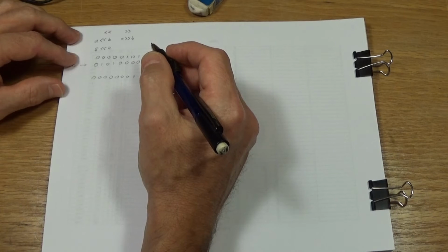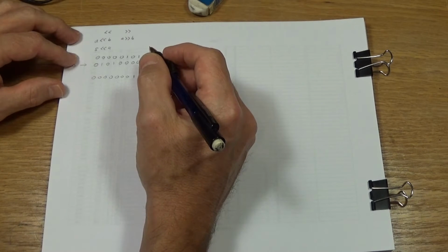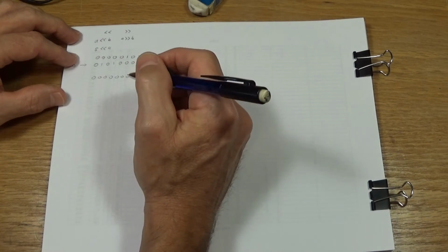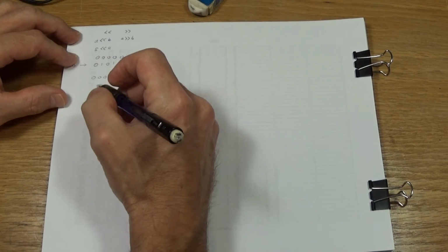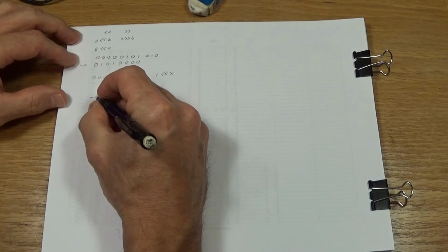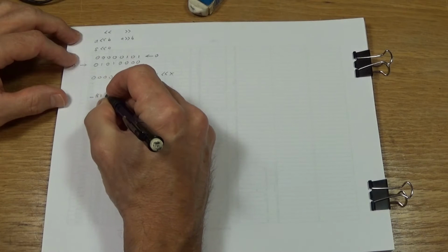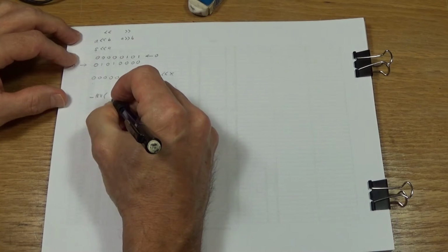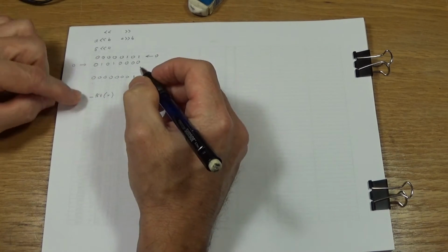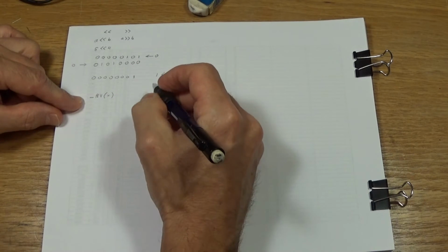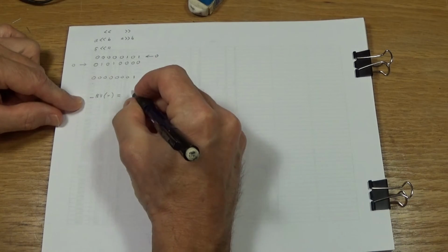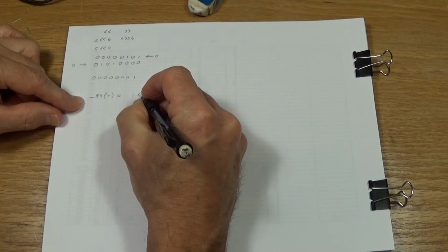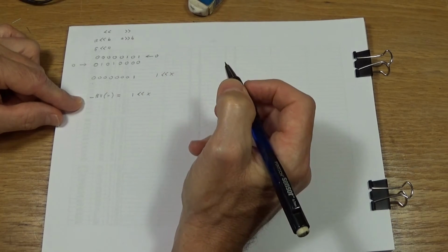Now in the compiler that I'm using here, there's a macro that's called BV, or bit value, and it looks like this: underscore B, capital V, and inside there's a number. And what it means is exactly this: 1 left shifted X positions.